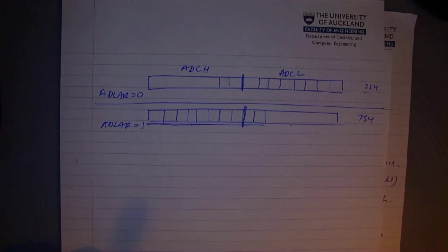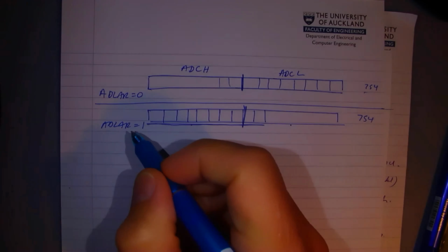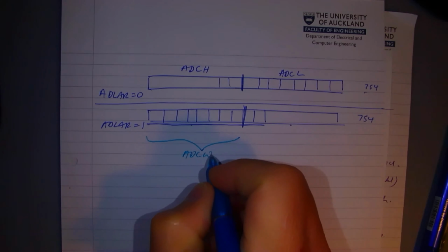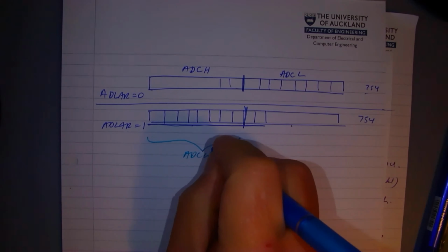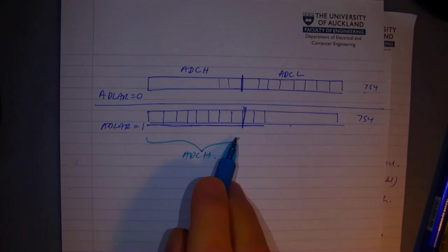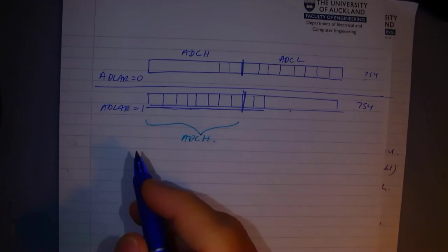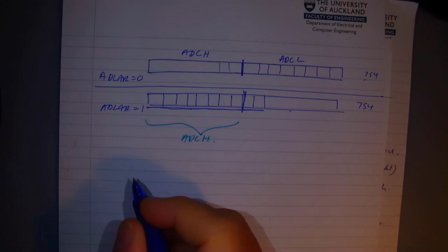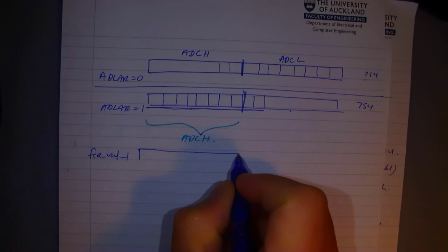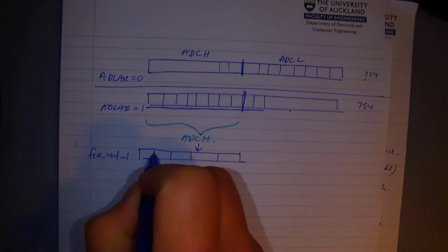Now in my function, I'm only returning this. I'm only returning ADCW. Sorry, ADCH, not W, W is the whole thing. ADCH. So I'm just returning those 8 bits there. And so what I'm doing is I'm reading it into a value. I called it FSR value 1. So it's an 8-bit number, and this has all gone into the 8 bits. So I've got all 8 bits.